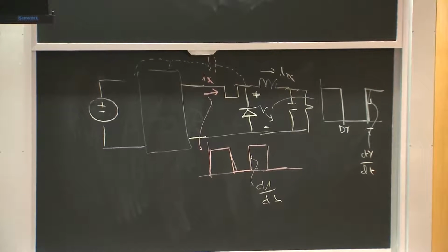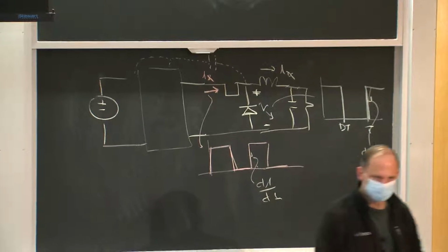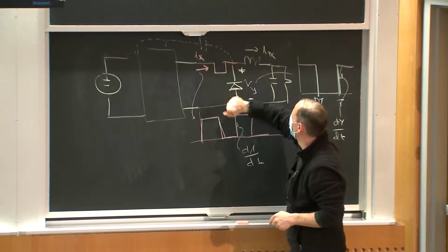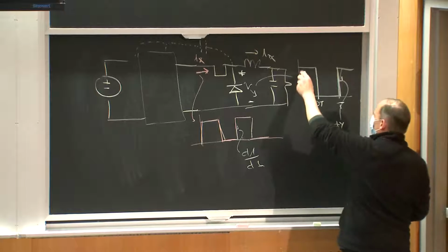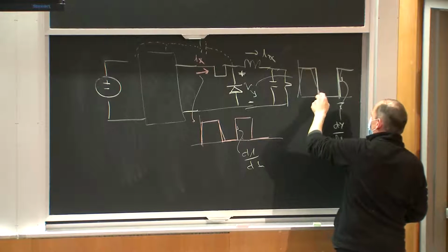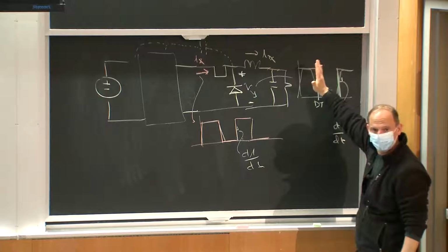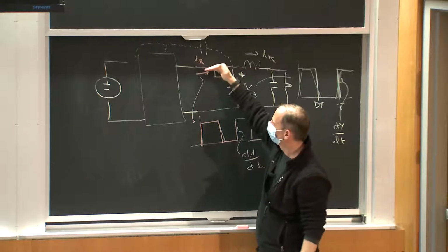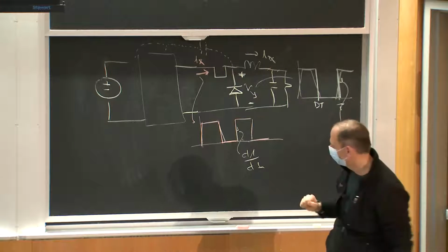So let's think about what's the impact of square wave switching. Because what are we going to do? Maybe if I use zero voltage switching here, instead of having a really steep waveform V_Y, maybe what I would have is a more slew rate limited waveform here, okay? And so what's the impact of this slew rate on dV/dt, or the slew rate on dI/dt, if I had lower dI/dt switching transitions on the fundamental waveforms, okay?